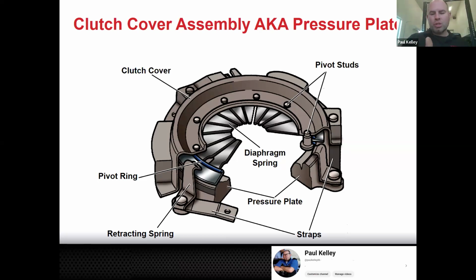The reason it's not pushing back up is because you pushed it down and that compressed the air, and it never really pressed on these diaphragm springs. So there's no spring trying to push the fluid back, which is trying to push your pedal back. It's all just been absorbed by the air and it'll just get stuck. So you ever jump in a car and push it to the floor and the clutch pedal stays to the floor? You got an issue there.